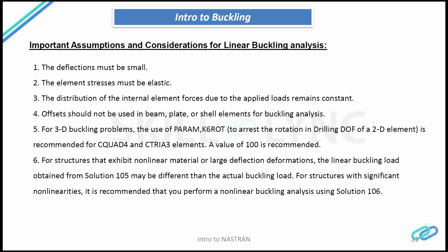And the second one is the element stresses. The element stresses must be elastic. It is obviously understood, since it's a linear analysis, the material behavior is elastic, and the distribution of the internal element forces will remain constant. So there is no major variation within the elemental distribution of the loads. It is what is expected.